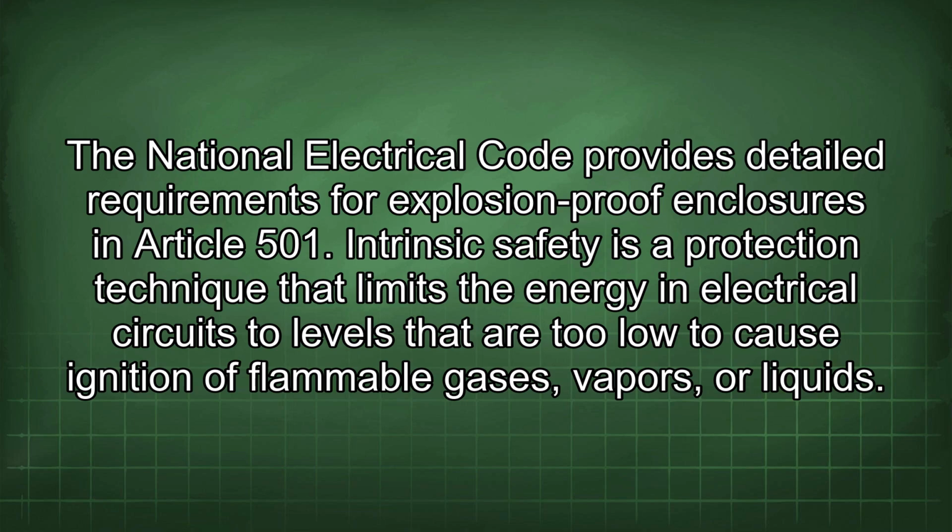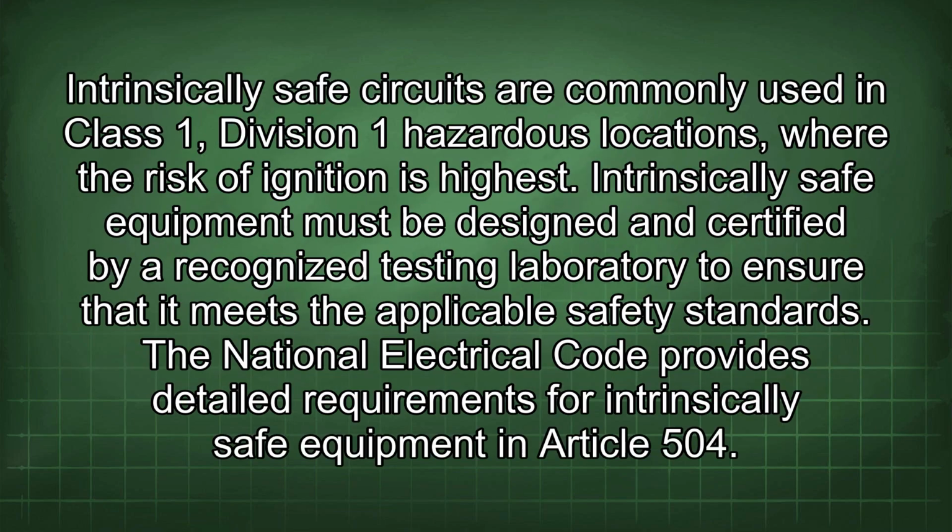Intrinsic safety is a protection technique that limits the energy in electrical circuits to levels that are too low to cause ignition of flammable gases, vapors, or liquids. Intrinsically safe circuits are commonly used in Class 1, Division 1 hazardous locations where the risk of ignition is highest. Intrinsically safe equipment must be designed and certified by a recognized testing laboratory to ensure that it meets the applicable safety standards. The National Electrical Code provides detailed requirements for intrinsically safe equipment in Article 504.